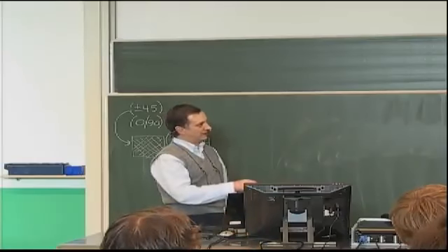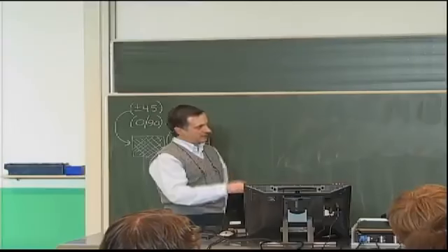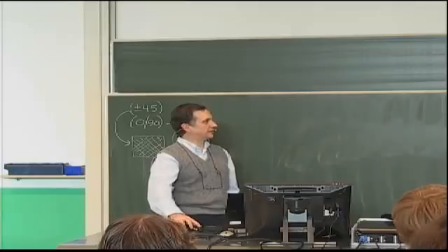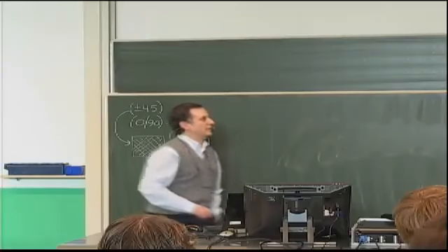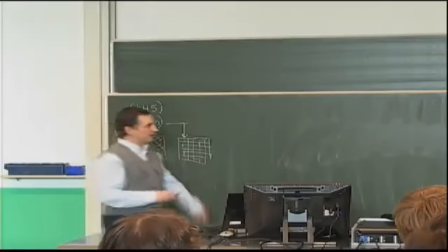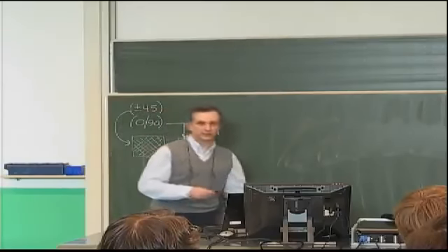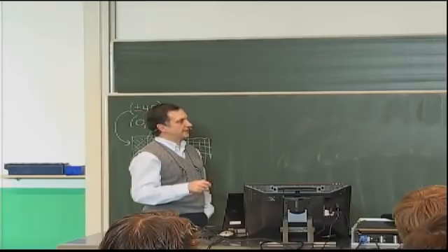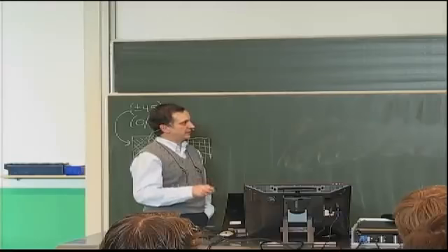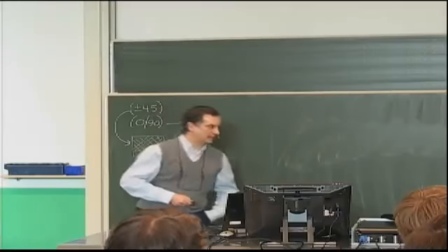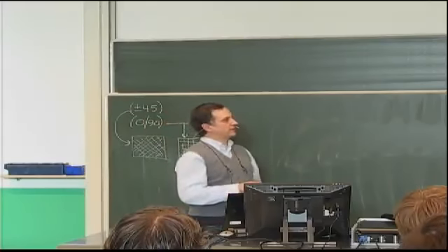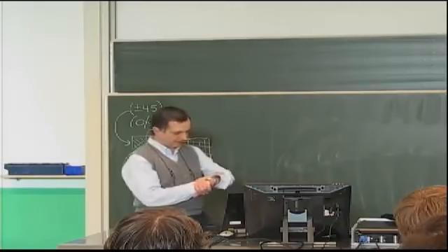And knowing my BMN, I can go back to my series expression here, substitute W in my governing equation on the left-hand side, substitute the BMN sine times sine on the right-hand side, and equate now the coefficients of the different terms that have sine m pi x over a and sine n pi y over b. When I do that, I will find now that my AMN terms, which is what I was looking for in the first place for the W expression, are given by this mess, as a result of which my W now, just by taking this and putting it in, is given at the bottom of this page, and that's valid for any xy location and for any x0, y0 location where the point force is acting.